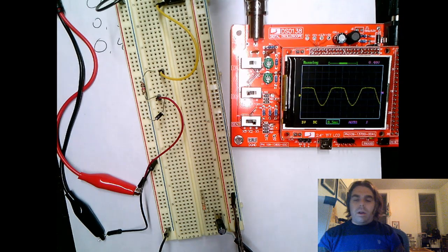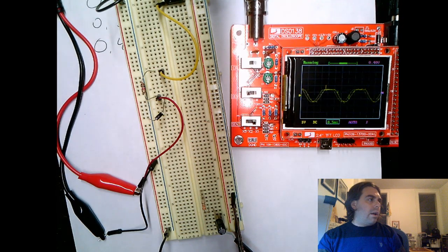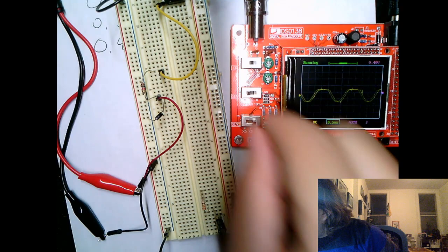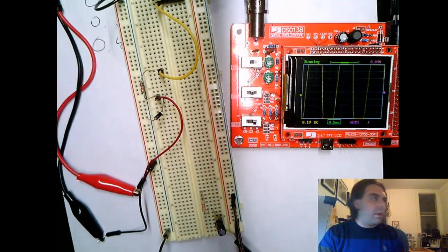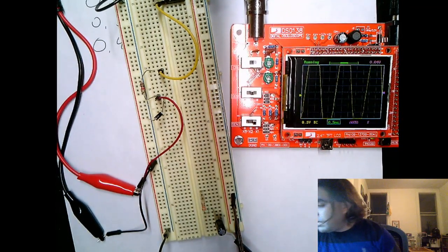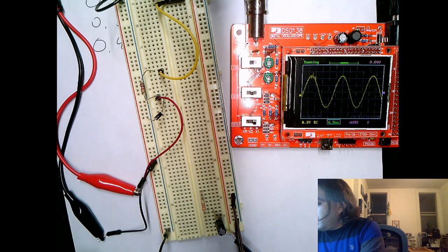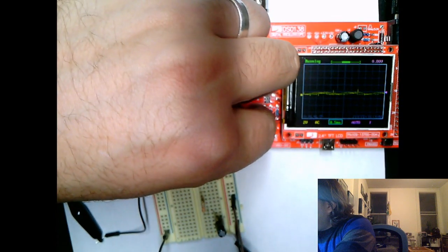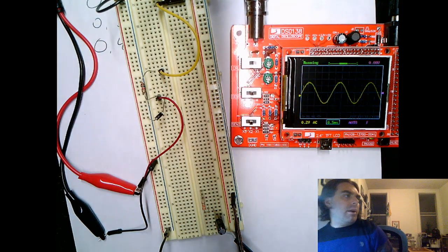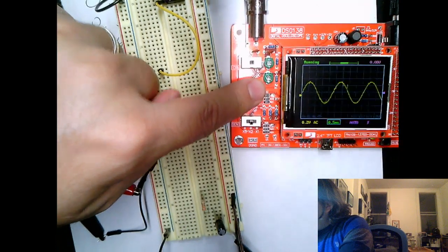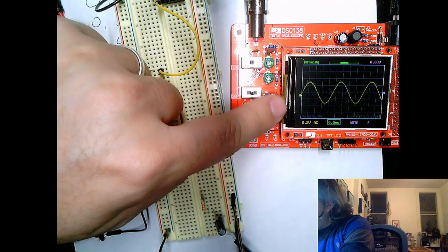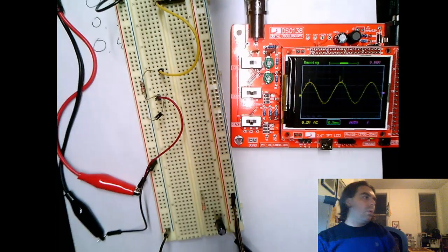And I'm going to actually look at this on a smaller scale, just so I can show you this. So I'm going to look at this as the 0.1 volt scale, right? Let me actually go to 1. I'll divide this by 2. So I'm looking at this. Yeah, okay. 0.1 here, x2 here. So basically every division is 0.2.